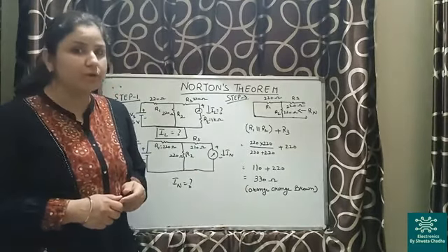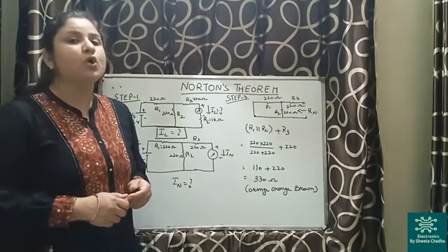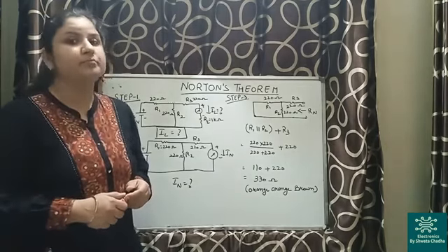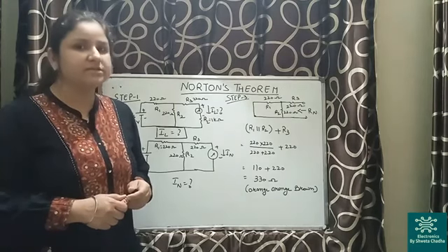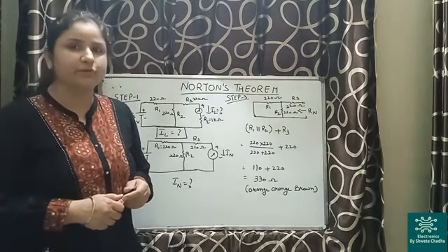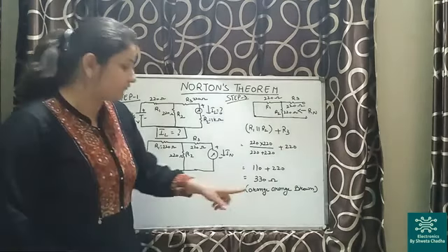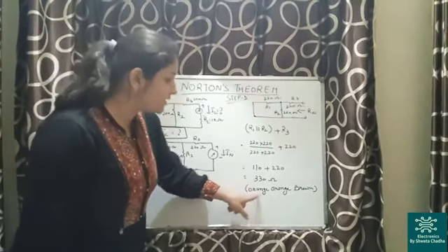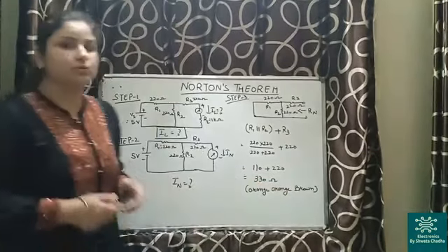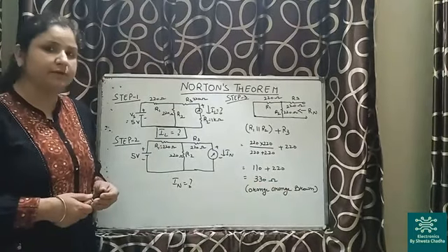So as per the color coding, the resistance will have orange, orange and brown till 3 colors. And yes, the fourth color can have any other value. For example, gold, silver or maybe no color for the tolerance. But the first 3 bands will be orange, orange and brown. So this is step number 3.